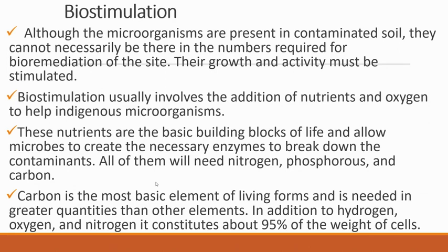Although microorganisms are present in contaminated soil or environment, they cannot necessarily be there in the numbers required for bioremediation of the site. Their growth and activity must be stimulated. So biostimulation usually involves the addition of nutrients and oxygen to help the indigenous microorganisms.